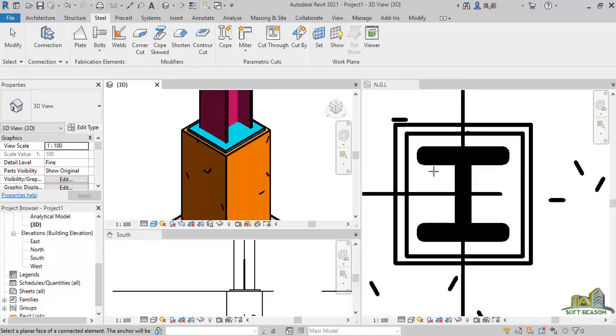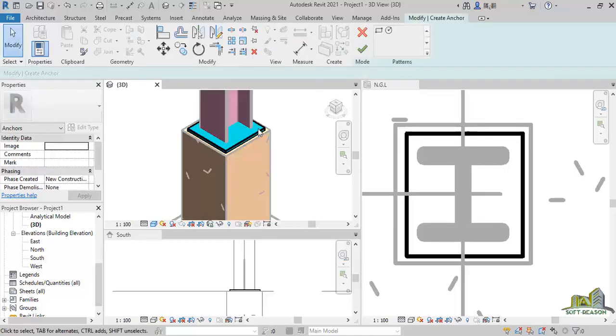You click this place to activate this view, and then select the surface of this place, just like this. Once the surface is selected, you now have to activate the rectangular drawing tool.